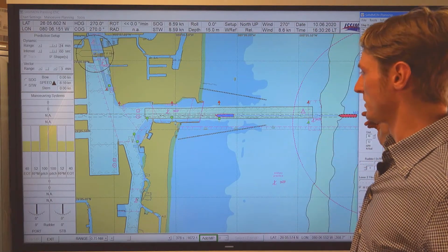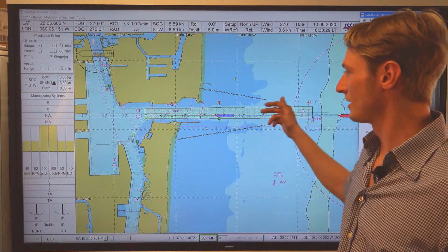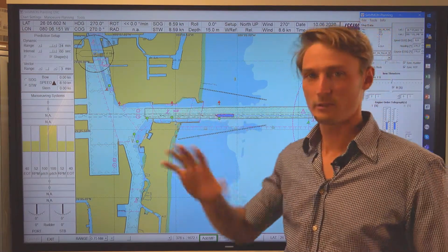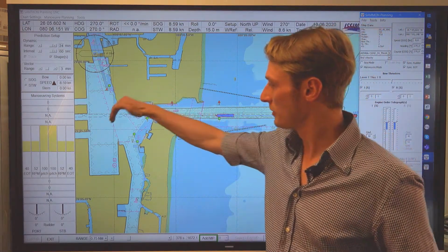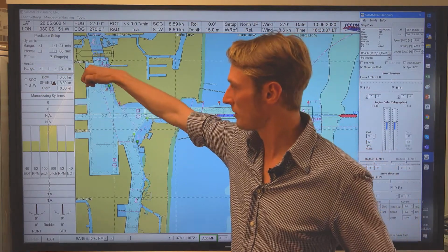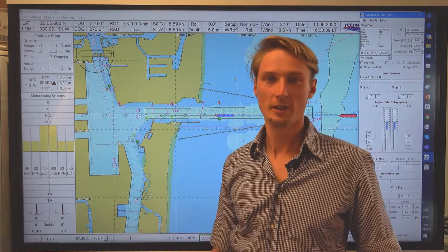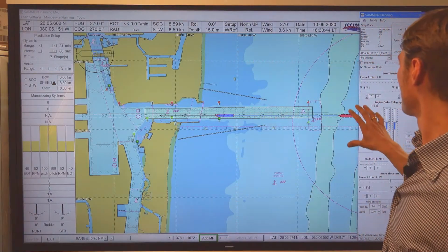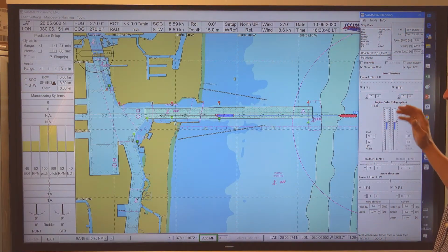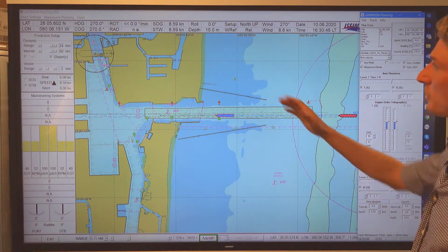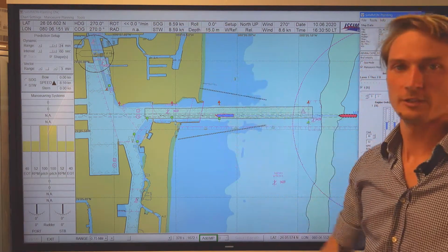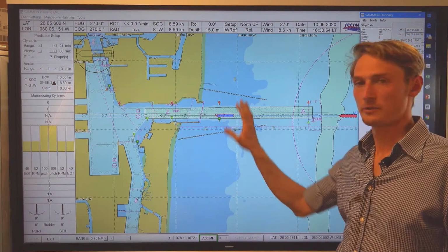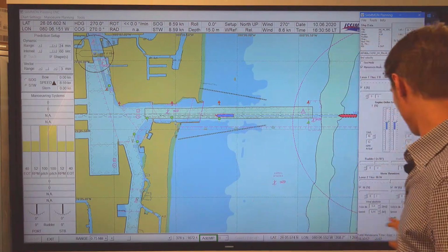And basically it's the task to enter the sea channel, to pass the breakwater at a speed of roughly 8 knots, turn to the south and then approach the stern by the starboard side until the ship is safely moored. At the beginning, outside here, we approach with the engine telegraph on set 4 and we have a speed of 8 to 9 knots. What we expect is a current setting from the south to the north with about 2 knots.